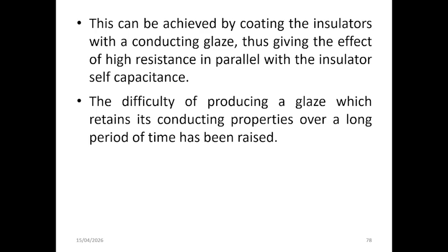The approach involves coating the surface of insulators with a semi-conducting glass, which effectively provides a high resistive path in parallel with the self-capacitance of each insulator unit, and this allows leakage currents to flow, helping to equalize the voltage distribution across the string by reducing the dominance of capacitive effects.